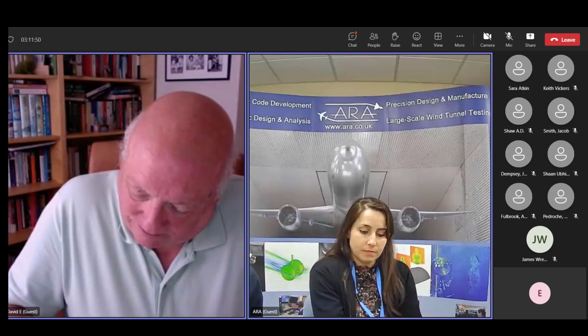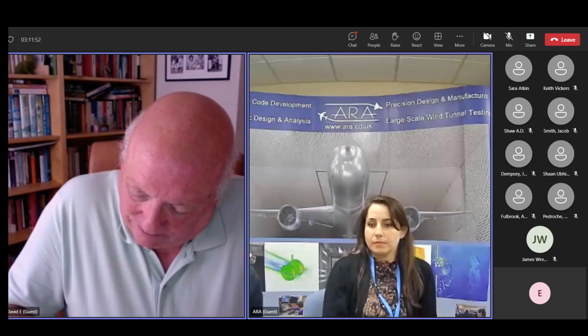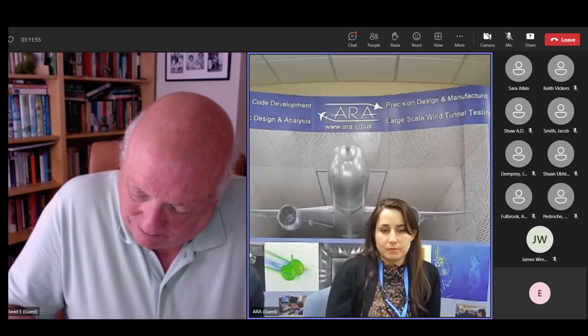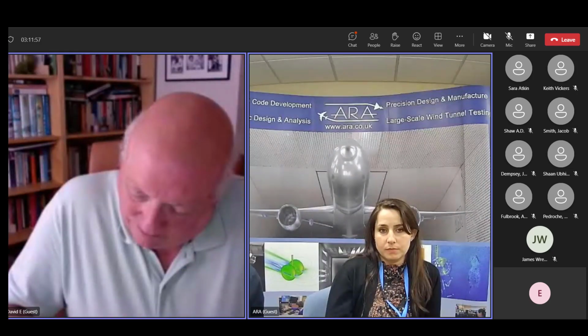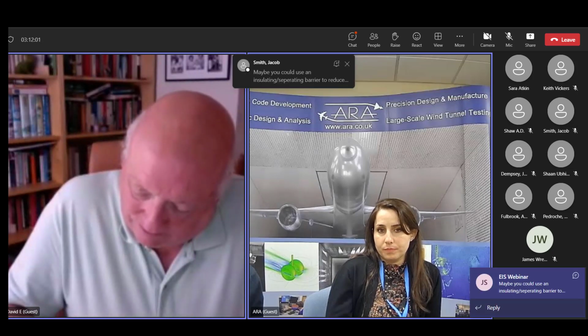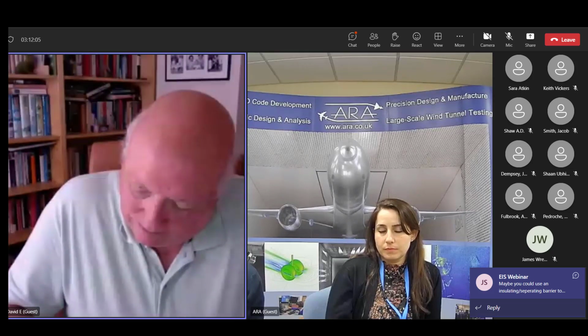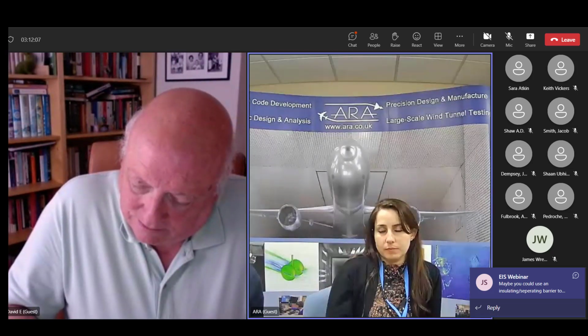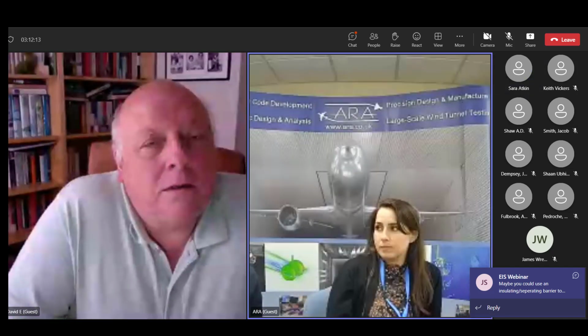I think the DSJP rig that we developed has some unique characteristics in terms of the way it handles air blowing through the middle of it and the thermal variations that we're now compensating for. That's fairly unique, I think. Most of our balances have air flowing over the actual structure.